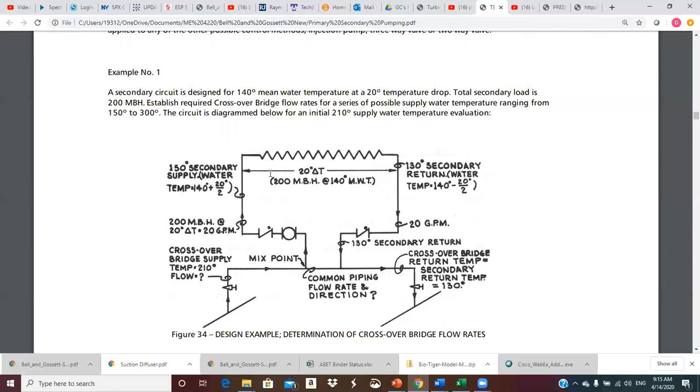Now, as temperatures get hotter and hotter, that's not quite right, because that 500 assumes that you have standard density water. You can do better. Q equals 500 GPM delta T is the same thing as Q equals m-dot Cp delta T; we just basically changed the units.